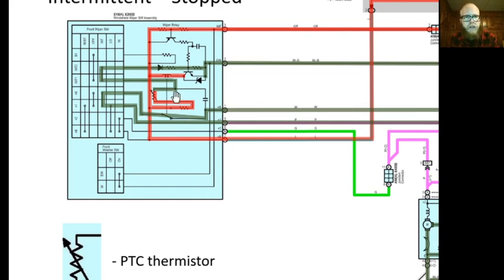In here, I also have an NPN transistor, a PNP transistor, and a relay. And this relay is kind of hard to see, but here's my coil. And what it's showing through this dashed line is that it acts on this switch. What it'll do is pull this switch up to this contact and supply power, which is coming in through that teal wire that goes up to the fuse panel.